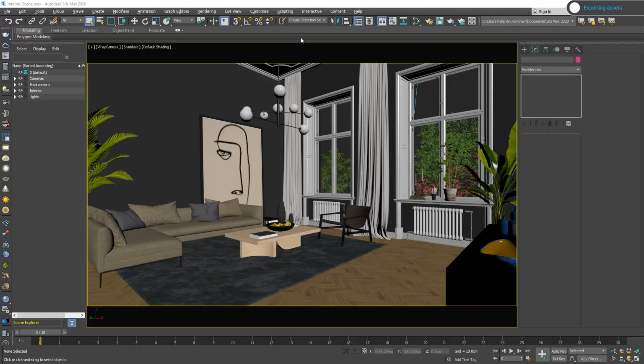I've already unwrapped most of the objects in my scene, but there are a few objects that don't have lightmap UVs. For them, I will use the Datasmith export, since the exporter will automatically unwrap them and it will preserve the hierarchy of my objects while keeping my objects in groups. I can also use the Datasmith exporter to export multiple cameras to use in Unreal. For this demo, I don't need that, since I'll create most of my cameras inside Unreal later on.